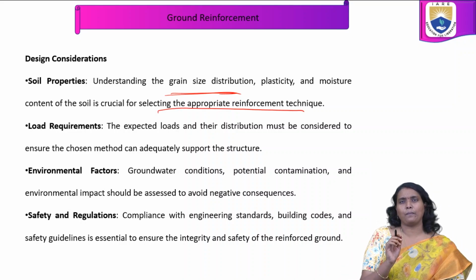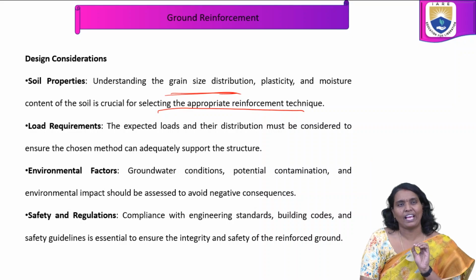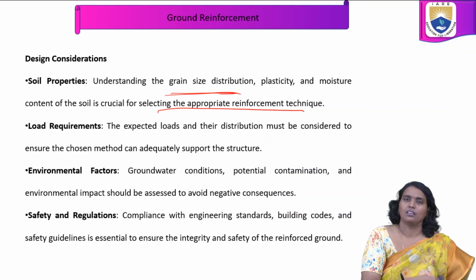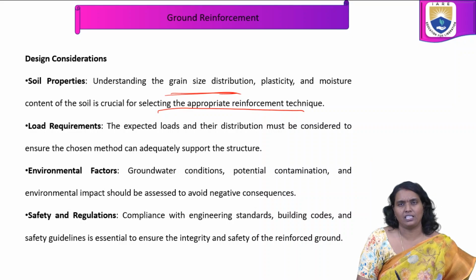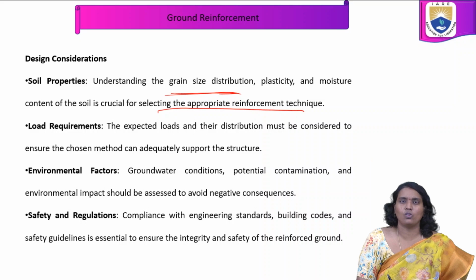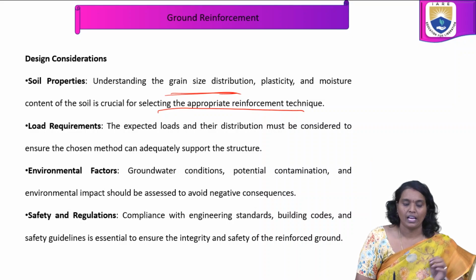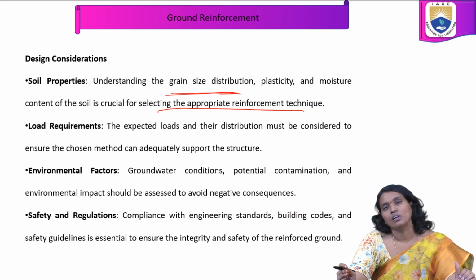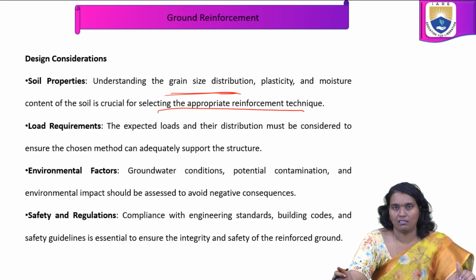Soil properties also play a role in choosing which type of ground reinforcement technique is suitable for the conditions. One more consideration is load requirement. The expected load and its distribution must be considered to ensure the chosen method can adequately support the structure. So the load requirements also play a role in selecting the type of technique for ground reinforcement.